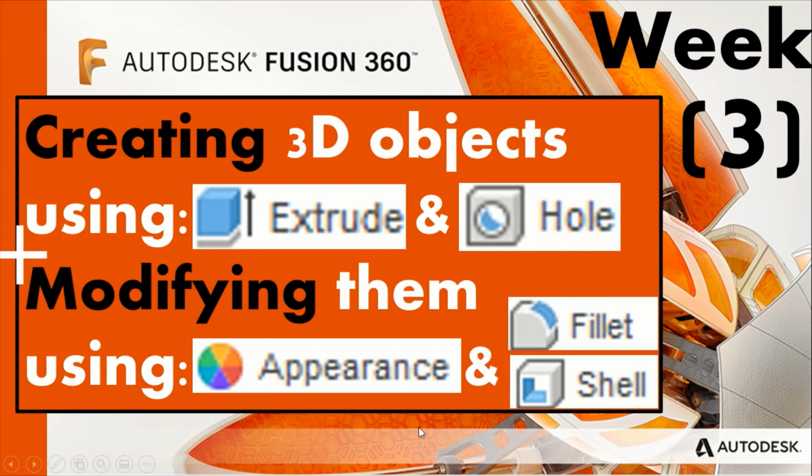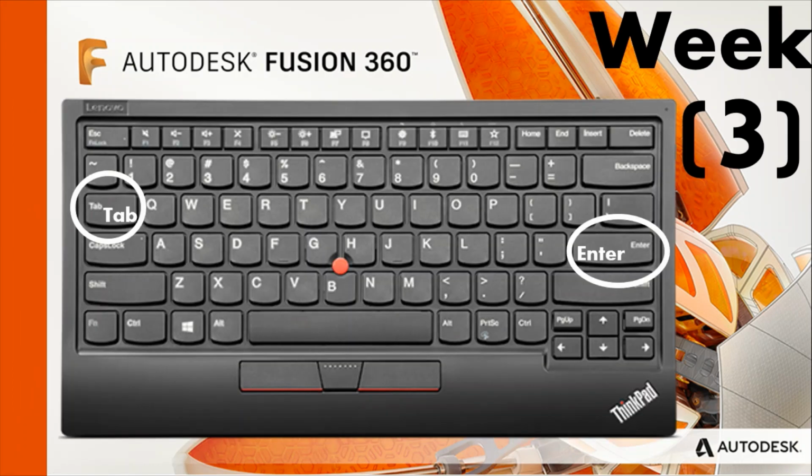Hello everyone, Assalamu alaikum. In this video you will learn how to create 3D objects using the Extrude tool, how to use the Hole tool, and also how to modify any object using the appearance tool, fillet and shell. So let's get started.